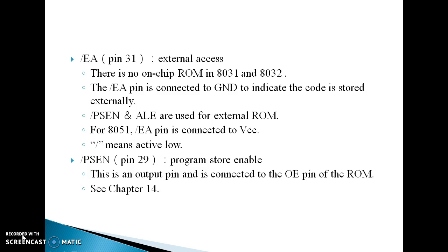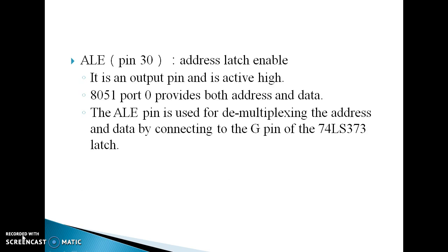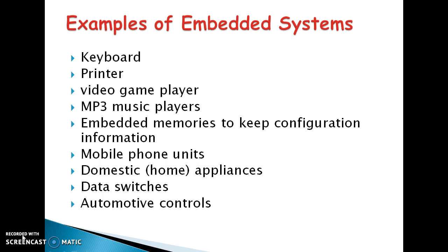And external access is used when there is no on-chip ROM, as in the 8031 and 8032. PSEN, that is program store enable, is an output pin and it is connected to the OE pin of the ROM. And ALE, address latch enable, is an output pin and it is active high.